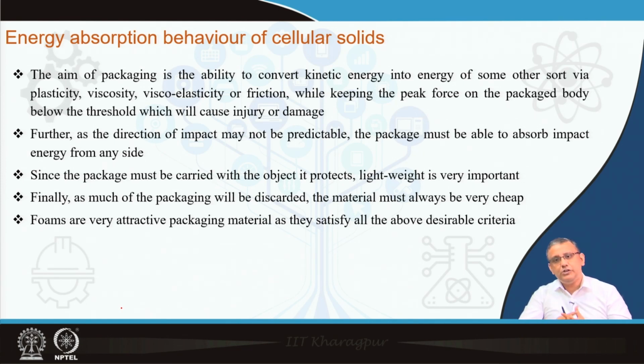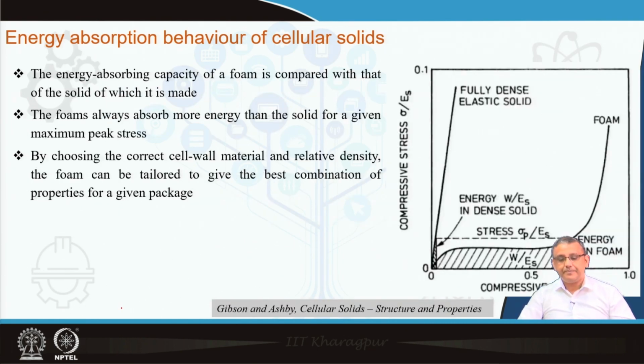Their sole function is to give protection, and they are sacrificial components, because if there is a crash, these foams or cellular materials will be sacrificed, and while doing that they will protect the occupants or the valuables inside. So the cost of the foams should also not be too high. These are the main properties required for the energy absorption behavior of foams or cellular solids.